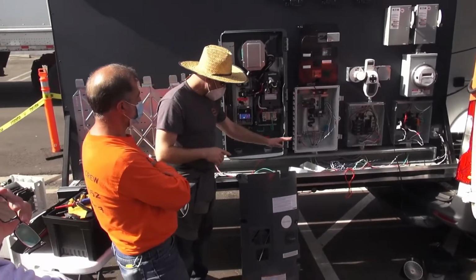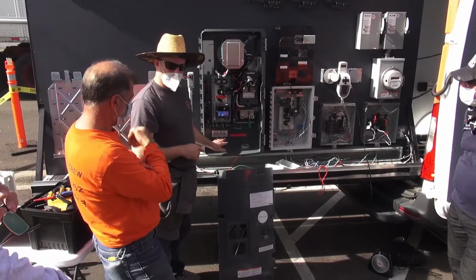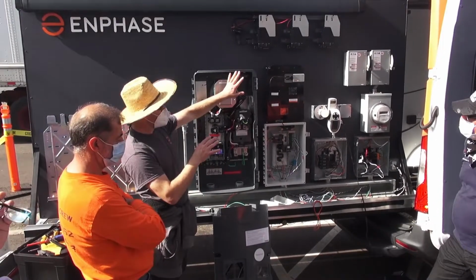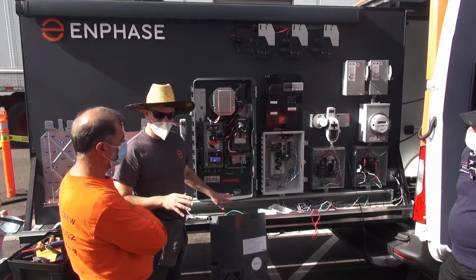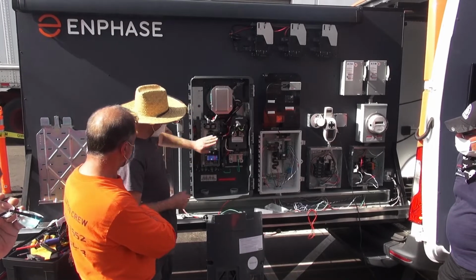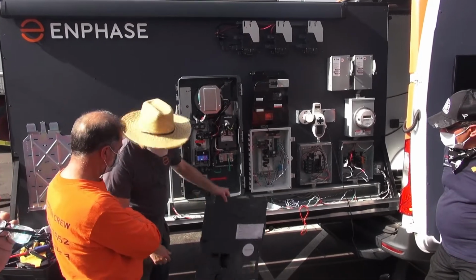With IQ8 PV, you must use a correctly wired rapid shutdown switch. This would be an incorrect configuration. So for today, this isn't a finished system yet. We've got to fix it and install it correctly. Okay, let's keep going. Neutral forming transformer.